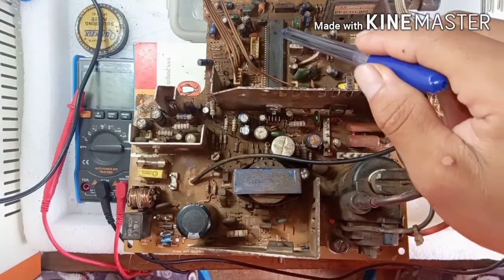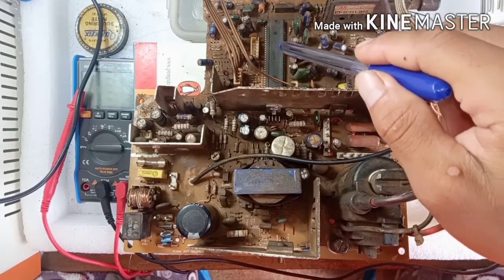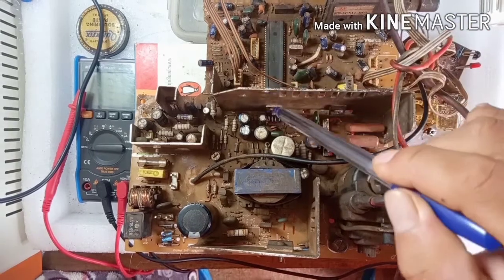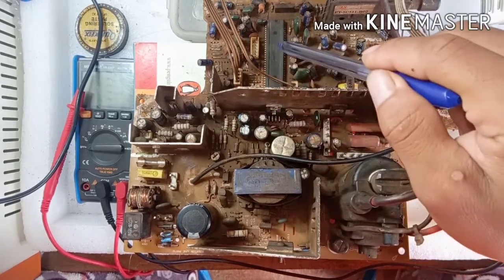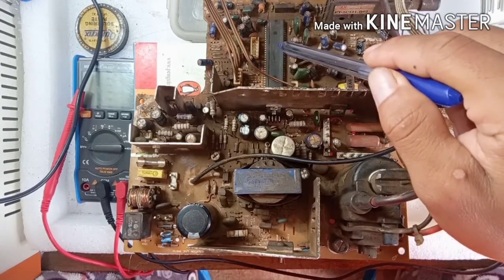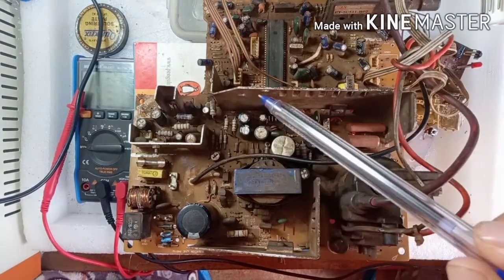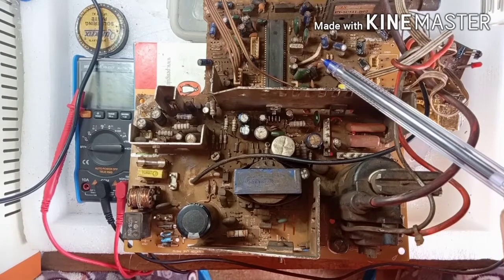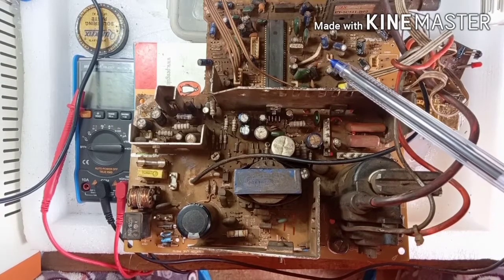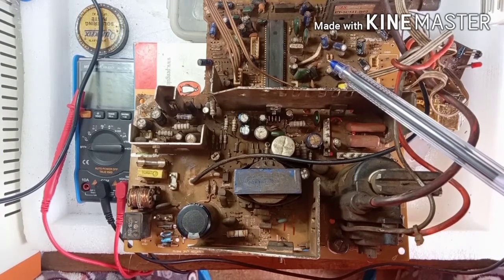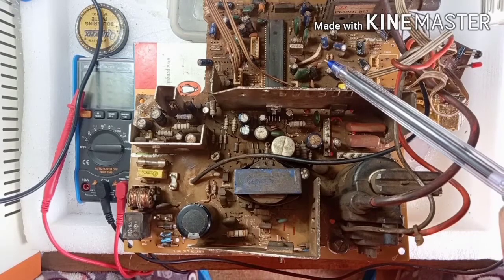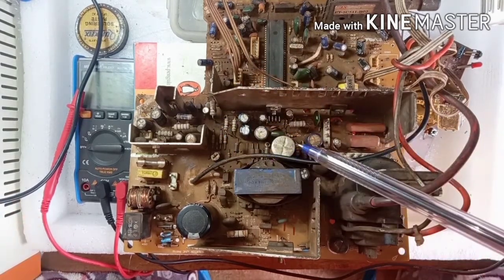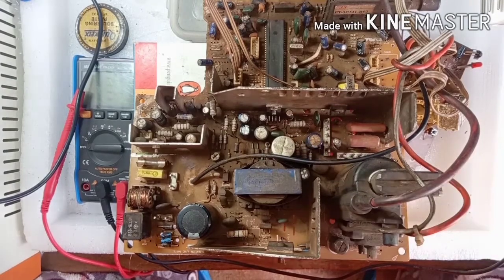That's the main IC processor, and as soon as it receives the signal sent by the regulator, it's like the vertical IC is asking the main IC processor through the regulator, hey main IC, I want to turn on, please help me. So at that point, the main IC processor will turn the vertical IC on. So our conclusion here is that the chain of connection or communication among the components might have been interrupted. So let's check if that's the culprit.